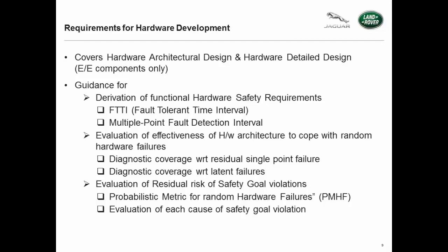Part 5 has guidance for derivation of functional hardware safety requirements. For example, from the system level, we might cascade fault-tolerant time intervals to the hardware, and these must be met when designing hardware components. And these next 2 bullet points address hardware failure rates.